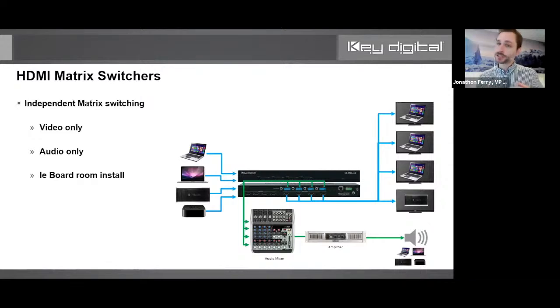use the audio outputs as a sort of input audio de-embedding. So you can have the 4 HDMI sources on the 4x4G, or 8 HDMI sources on the MS 8x8G feed in, and you can use those 4 or 8 audio outputs almost as input audio de-embedding, and they'll stay put. If you're not sending the command to switch both video and audio, and you're not sending the command to switch audio only, then audio stays put, right? So you could use the video only switching command.